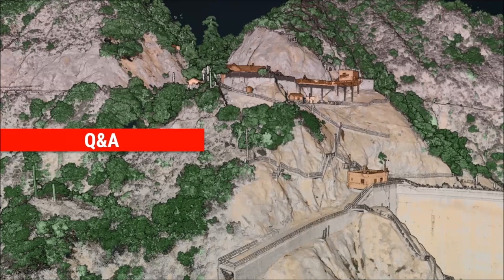We still recommend doing an IE type, Inertial Explorer type post-processing of our trajectory, coupling the GNSS and the IMU data while getting refinement to the GNSS observations through base station observations, is really a key first step to creating quality point cloud data. With that said, Spatial Explorer 6 has our NavLab embedded into it,